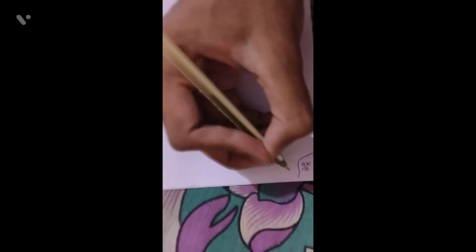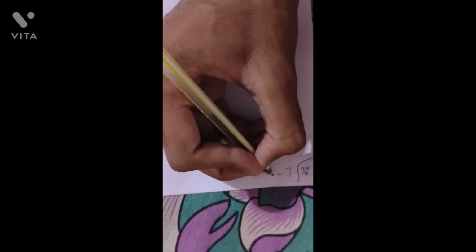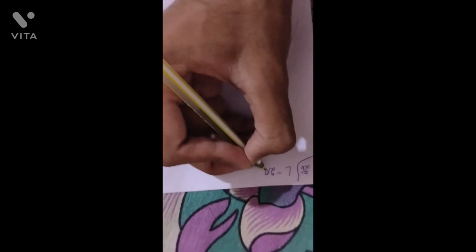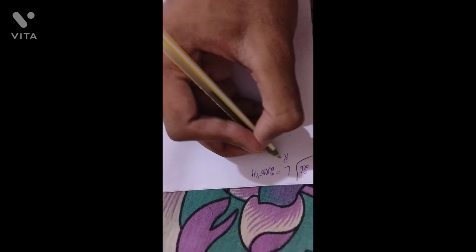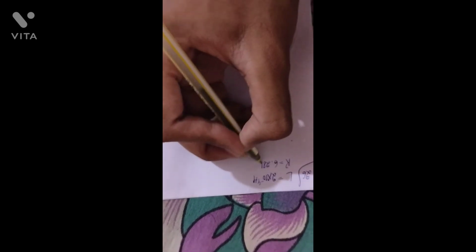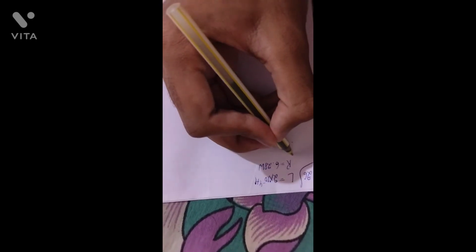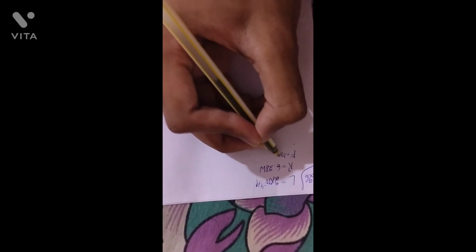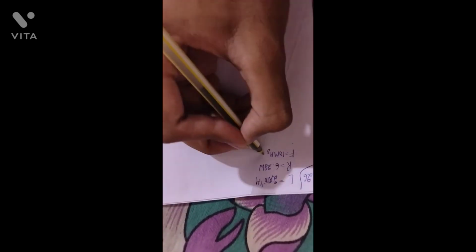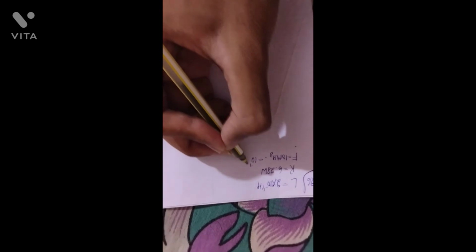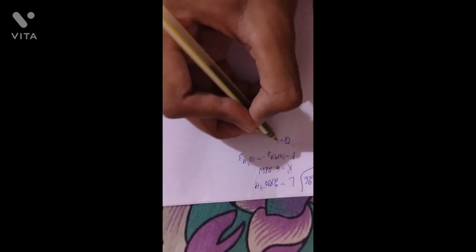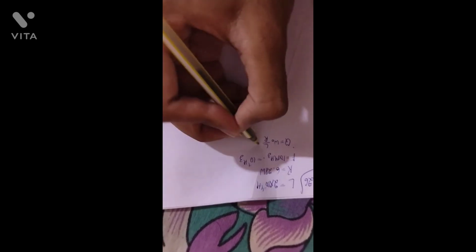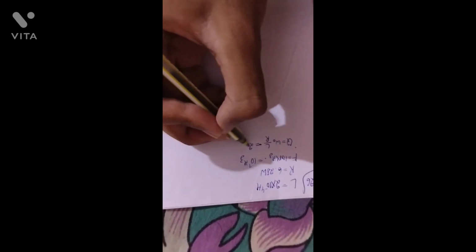So they have given L equal to 2 into 10 to the power minus 4 henry, R equal to 6.28 ohm, then f equal to 10 megahertz, that is equal to 10 to the power 7 hertz. Okay, then Q is equal to omega naught L by R, which is the formula, therefore it is 2 pi f L by R.